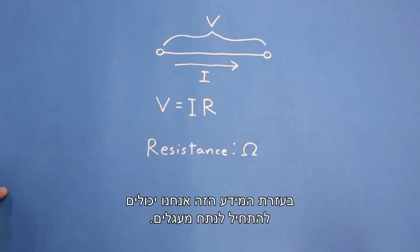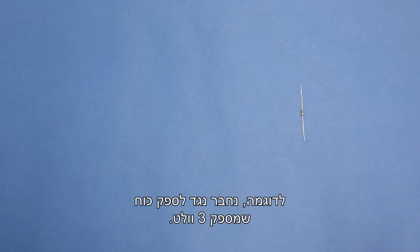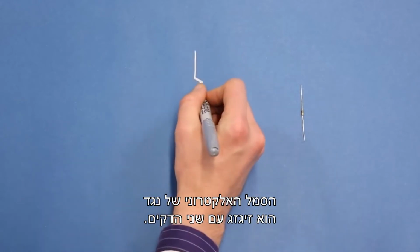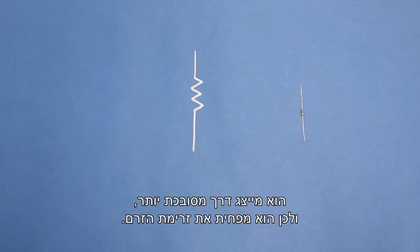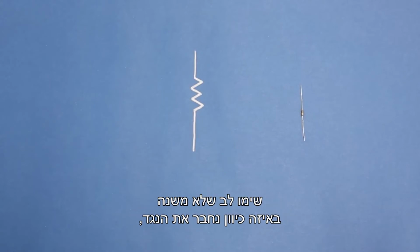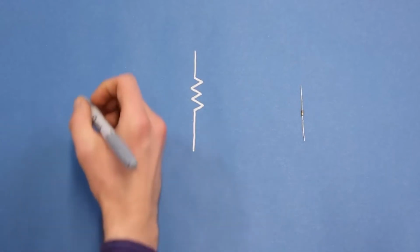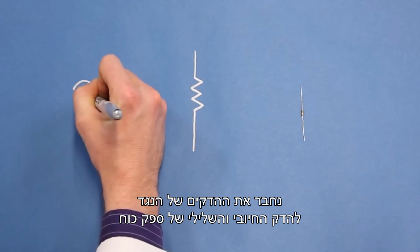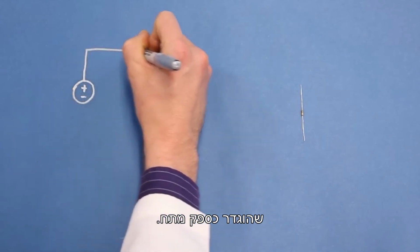With this information, we can begin to analyze circuits. As an example, we'll connect a resistor to a power supply that provides 3 volts. The electronic symbol for a resistor is a zigzag with 2 terminals. It represents a more complicated path and therefore reduced current flow. Note that it doesn't matter which way we connect the resistor, it will do its thing regardless of orientation. We will connect the terminals of the resistor to the positive and negative terminals of a power supply that's been set to act as a voltage source.